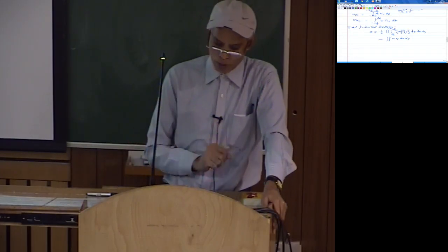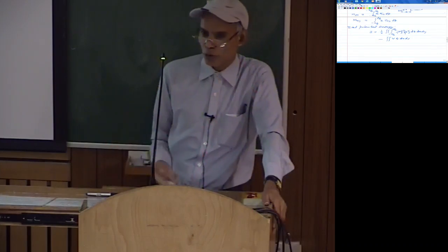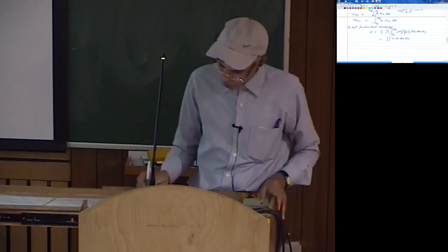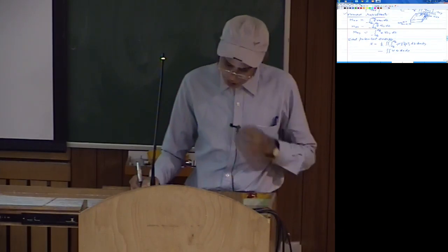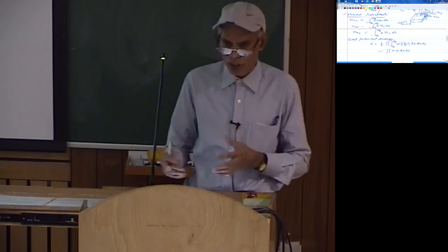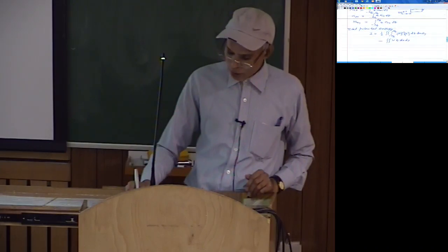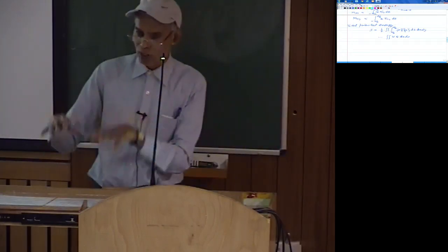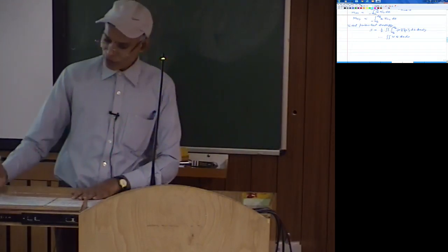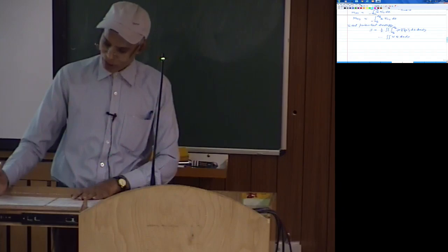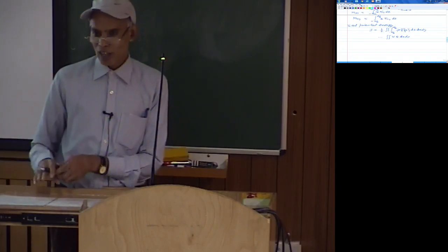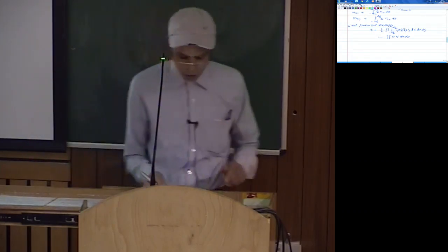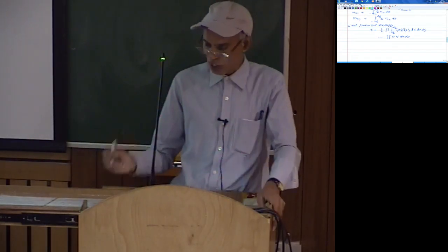Still for plate bending modeling, it is the difference of those two loads which goes as Q in the formulation. So this is the distributed force. In addition, because we are actually interested in the finite element, on the boundaries of that you will have forces, and since you are talking of a plate where there are transverse forces, expect the reactions from the surrounding elements. One is the transverse reaction, and since your stresses are distributed, also reaction moments. So you can have the transverse reaction force.